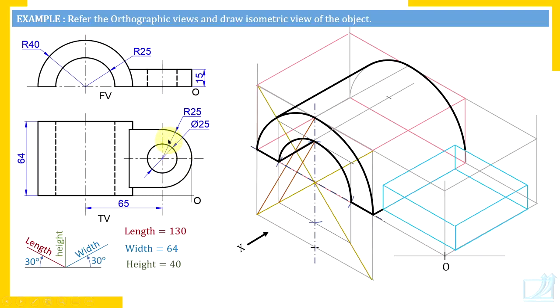So let's do that. Look at the center lines. Top surface. Focus on the top surface of the plate. On this top surface, draw these two center lines. Now this semicircular edge is in the top view. That means this center line is parallel to the length axis, because in the top view the horizontal axis is the length axis and the width axis is vertical. So this vertical center line in isometric view should be parallel to the width axis. This is very important.